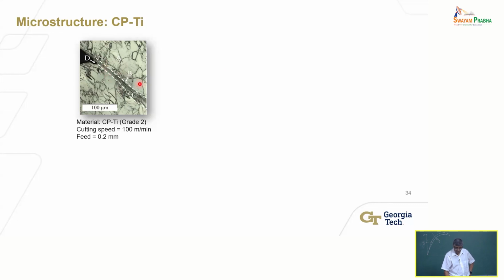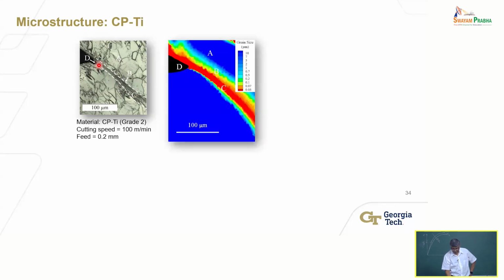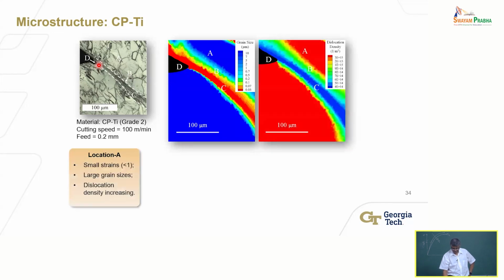There I can predict what the grain structure is. The reason this region is highly strained: when it's highly strained, the grains are going to be deformed a lot. You take a grain and you deform it excessively, you would expect to break up that grain somehow into much finer particles, for simplicity. It's not a technically accurate way of describing it, but conceptually that is what is happening. So indeed, you can simulate that using these types of models. And that's what we have done here.